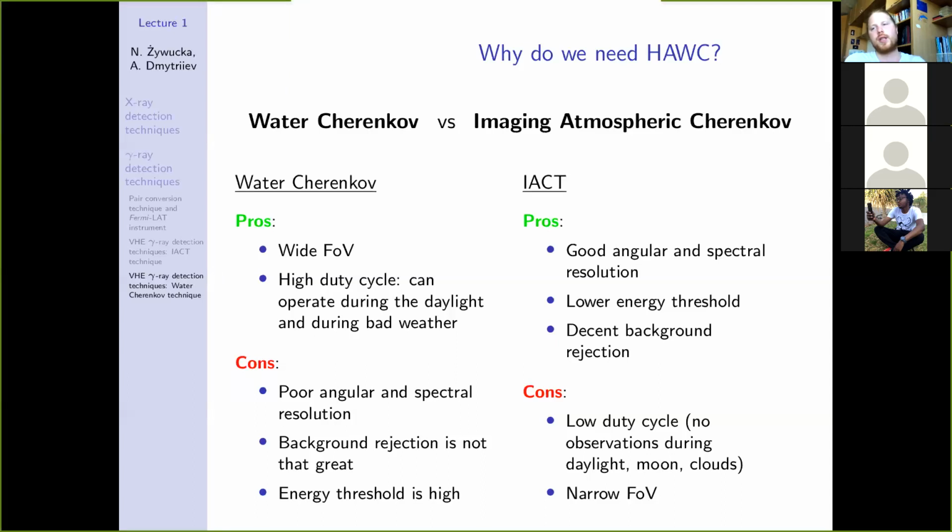But also because the photosensors like GAPDs or the photomultipliers are extremely sensitive to low light flux, so you will be destroying your PMTs or GAPDs with daylight. You cannot use them even during moonlight, it's tricky. Only GAPDs, because of adapting voltage, but PMTs will be burning.